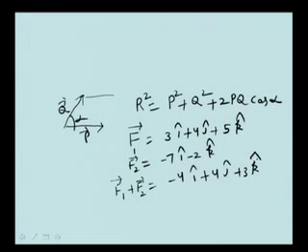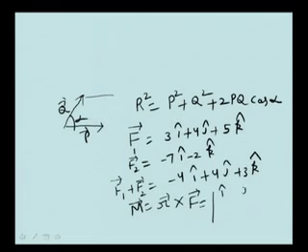Similarly, if you express the force in the form of components, i, j, k are the unit vectors along three orthogonal directions, that is the x direction, y direction and z direction. Now, given forces, you can find the moments also. r cross F is the moment. This can also easily be found out; you know how to find the cross product. We can have r cross F equal to i j k in the form of a determinant. This row is Rx, Ry, Rz, and this is Fx, Fy, Fz.